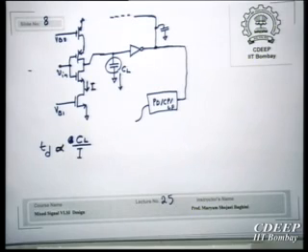Because that won't affect. Has anybody started design? Okay. But I don't think it will affect the design, right? Because anyway, you are getting right now small delays compared to the value which is required. What is your stage delay? Suppose one stage delay. How much is it? Just one inverter, without any extra load. 1.1 nano? Okay. 1.1 nano.